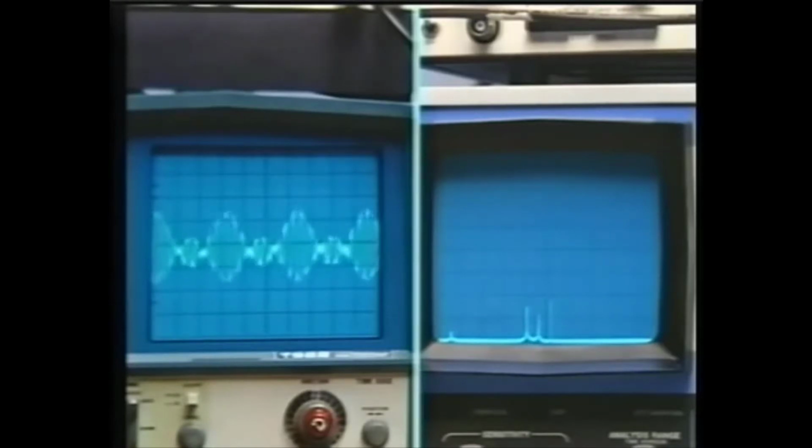And Sandy had also commented that we can change the carrier level, and let's do that on the modulator box. We could do that either by changing a DC offset on the modulating signal or by changing the amount of carrier that's injected. And as we decrease the amount of carrier, in fact, going down to no carrier at all or almost no carrier, that's suppressed carrier.